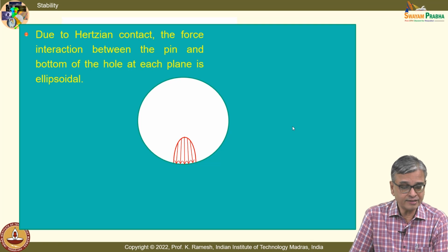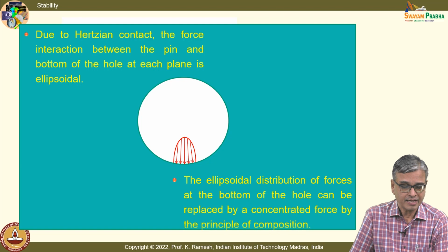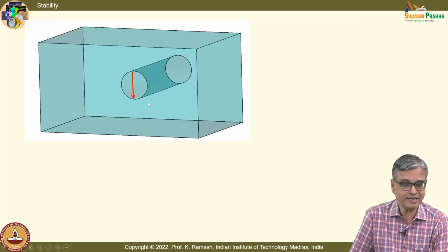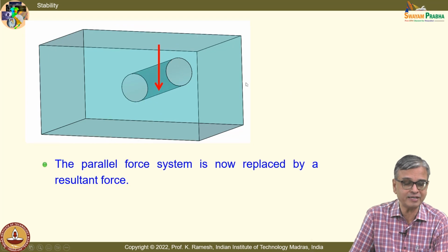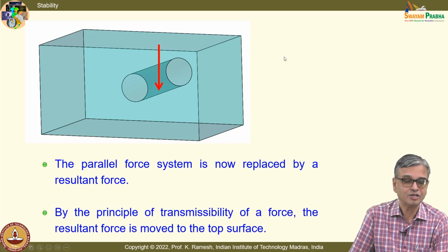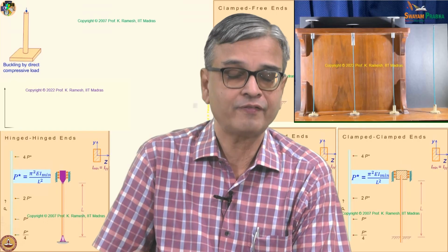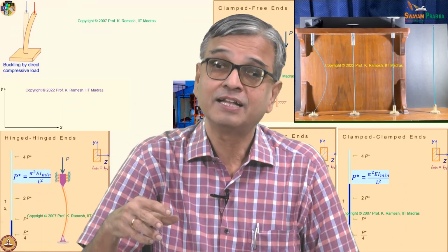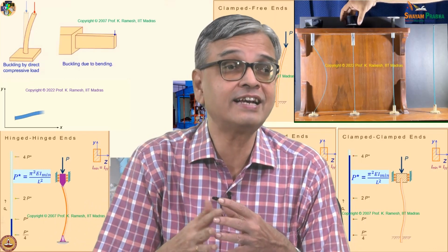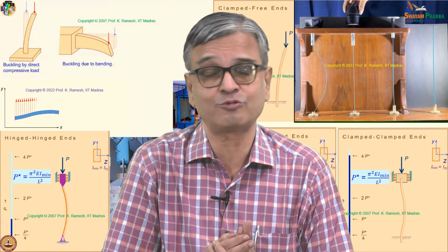You model this by a resultant, as a single concentrated force, then replicate this concentrated force along the line, take an equivalent value, then use the principle of transmissibility and move it to that point. So a simple problem where you have an end load put like this, when you physically translate it, has many aspects added to it.